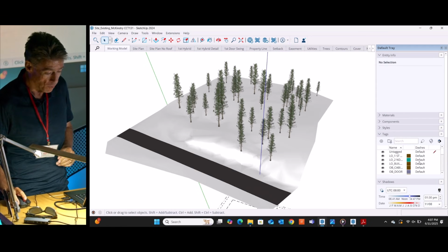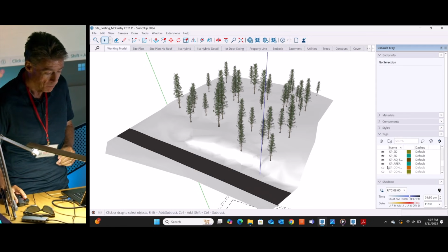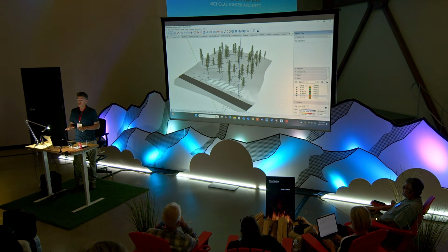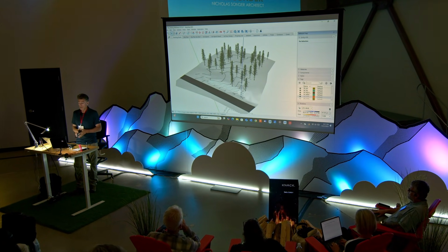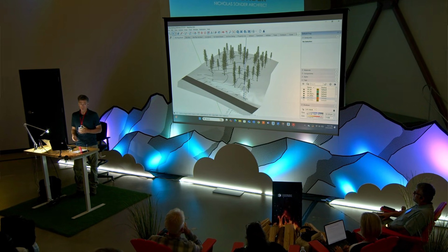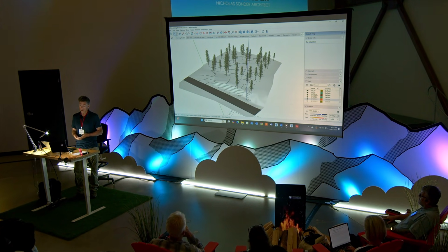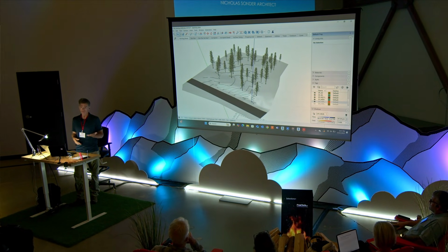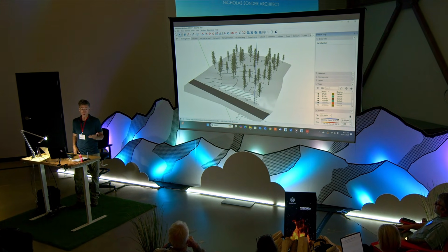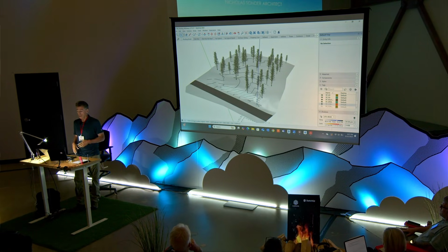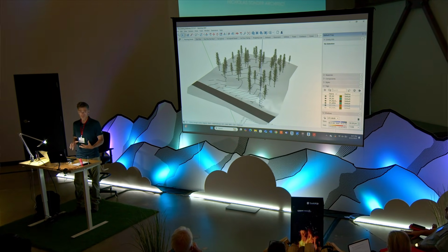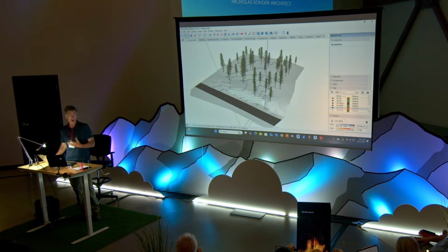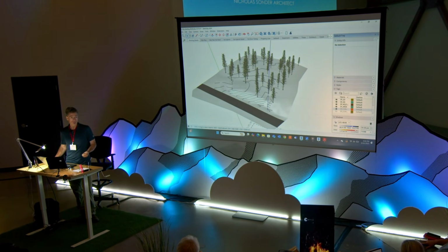The contours are there, they're just hidden underneath. Click those on, you can see them. This site, for our area, is relatively flat, which is somewhat rare. There's usually a price premium associated with that. They're also directly on the golf course. But it allows for ease of access, level driveways, parking. Those are all things in snow country we have to be really careful of. In this case, they had a really good position for view and solar exposure, so we're able to keep a lot of sun on the driveway and the garage doors so they don't bind up in the winter.